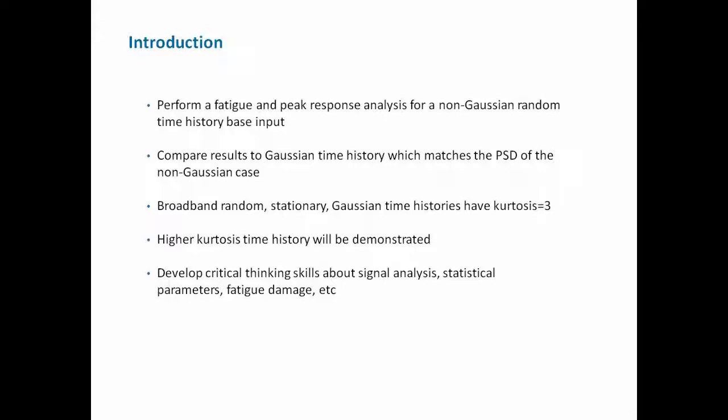Now sometimes in contrast we generate pure sine time histories, and a pure sine time history has a kurtosis of 1.5. But anyway, the class of non-Gaussian random time histories that we're concerned with in this unit will have kurtosis greater than 3.